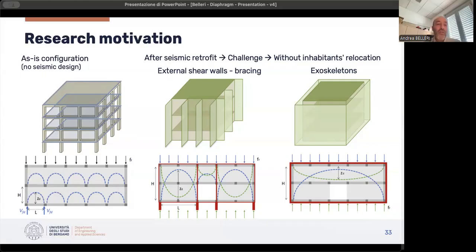And so we are forcing this load path of arches to increase in size and also in load transfer. So in this case, the load transfer increases, the compression in these arches will increase and could trigger failure of these blocks.